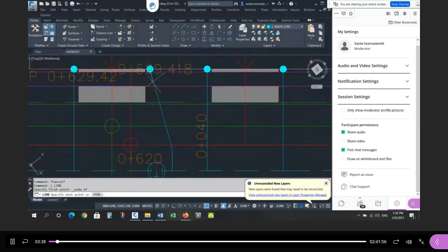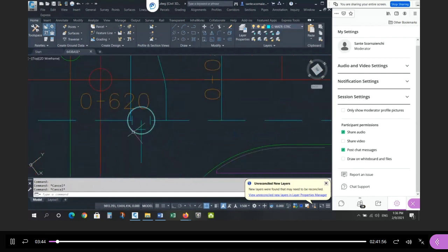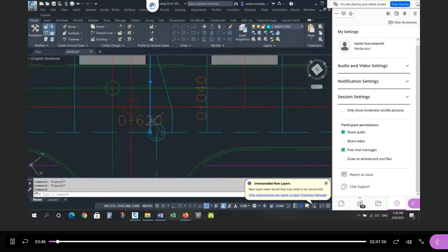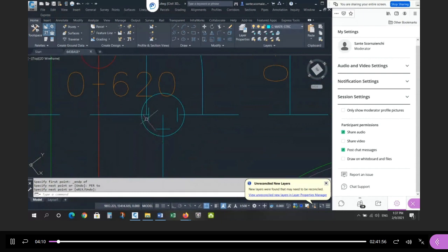Another common mistake was here, perpendicular to the water main. When you draw that service connection, it's in the structure as well. So then you have a choice of either moving it to this side a little bit, to the outside. That works, that's fine, but now you're getting close to the sanitary maintenance hole. So I chose my design. This is not wrong, but I think a better solution would be to go around the structure on this side. The typical from the location of the curb stop perpendicular to the pipe will put you right in the structure. So that's not going to work. So you either have to move it out to this side or around to the other side.